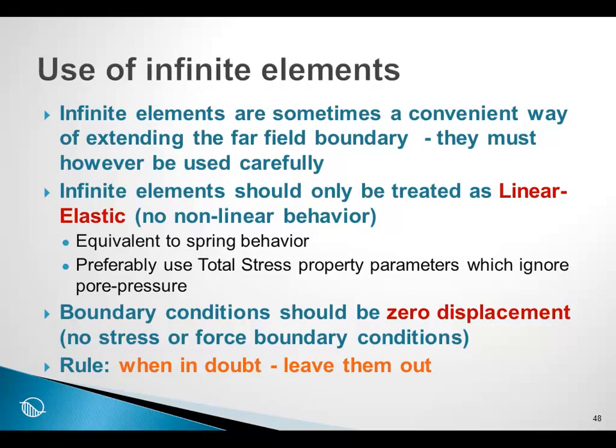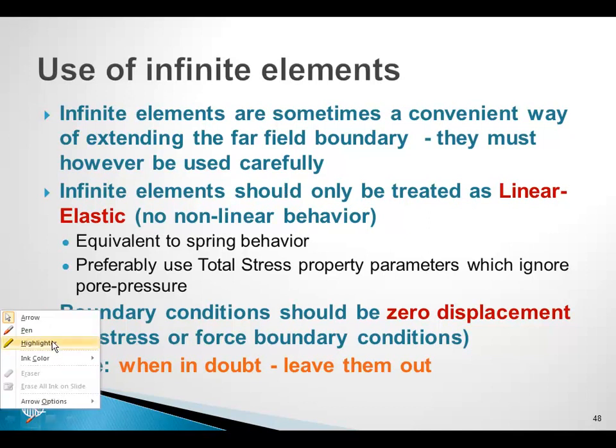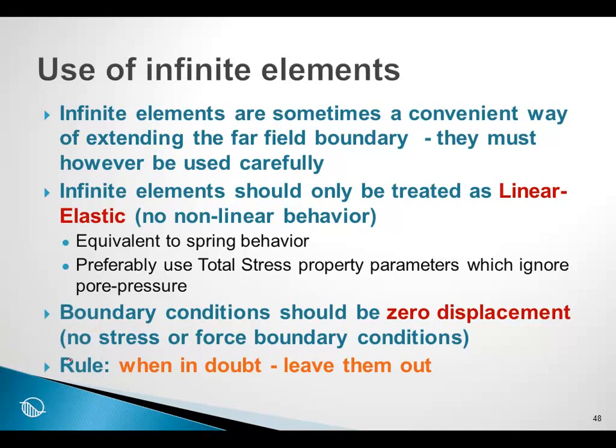Most importantly, however, is that the boundary condition should be zero displacement. Repeating, they should be zero displacement. We should not apply stresses or forces to infinite elements on the boundaries. They should be zero displacement. Even specifying a non-zero displacement is not a good practice with infinite elements.